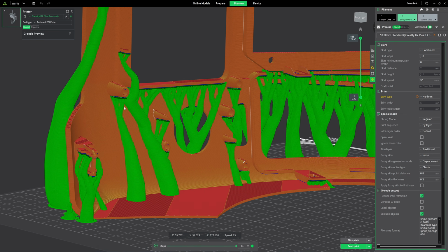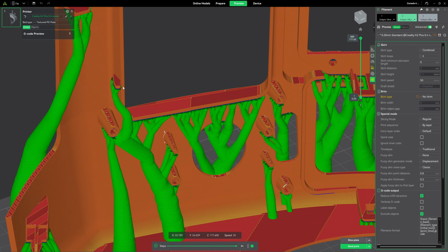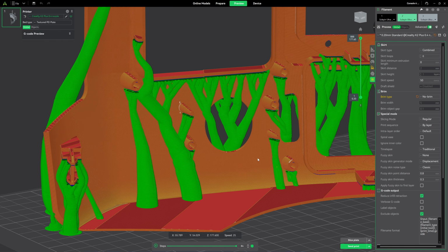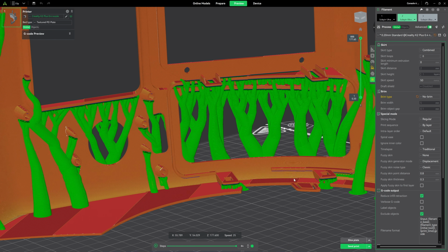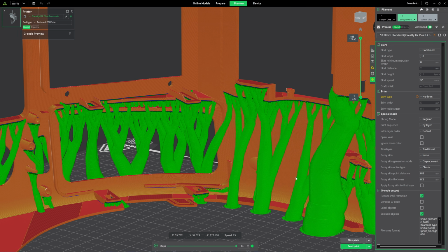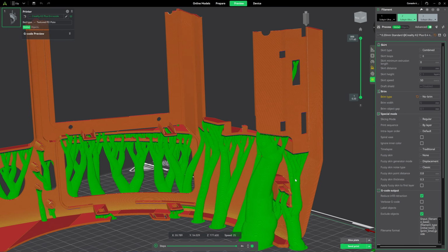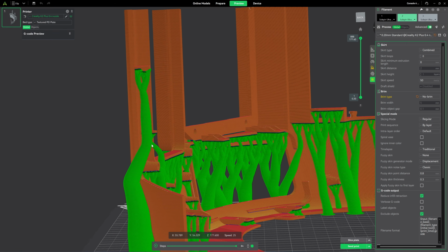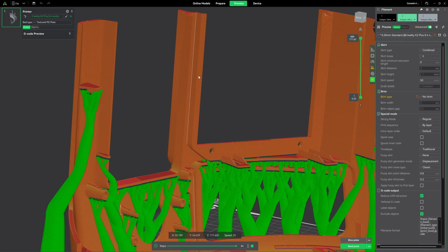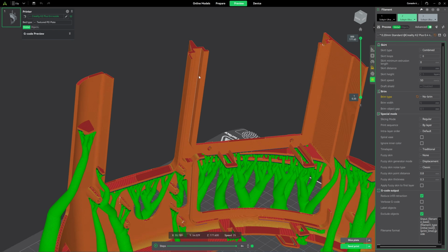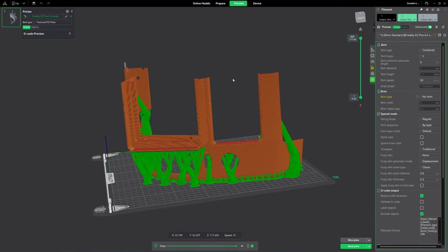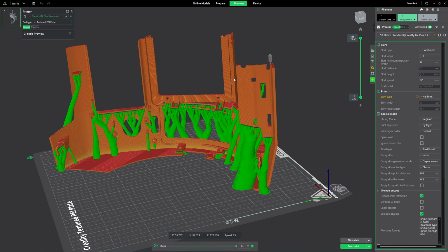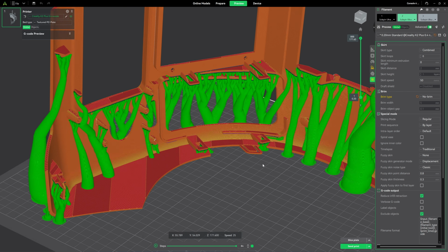However, I won't be doing the printing in this video. I first need to design a proper mechanical joint to connect the two halves securely. The bezel is very thin and even the original injection mold part already feels flimsy. Each half will take over 10 hours to print, so I only get one shot at trying. I will need some time to figure out how to join a bezel this thin, but I already have a few ideas in mind.